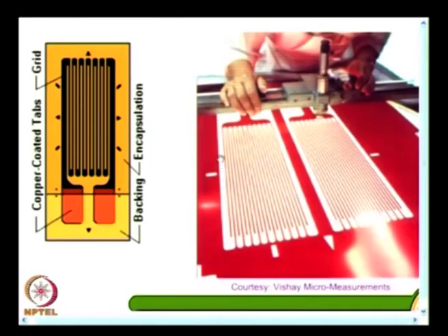We have right now seen making a resistance of 100 ohms is very difficult, it is not so simple, it requires technology. If I go to metal foil gauges, I can make the foil as thin as possible. So, I can increase the resistance comfortably. And remember, when you look at the foil like this, see, this is a metallic foil, but when I am going to have a very thin foil, even a metal thin foil is fragile. So, handling becomes very sensitive.